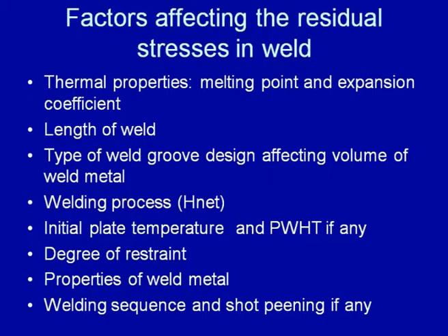Then the welding process. The effect of the welding process on the residual stress can be understood from the fact that each welding process offers a different energy density. Those processes which are of low energy density will be supplying more heat to the plates being welded, and the increased amount of heat means a larger area will be subjected to the expansion and contraction during the welding, which in turn will increase the possibility of having larger residual stresses.